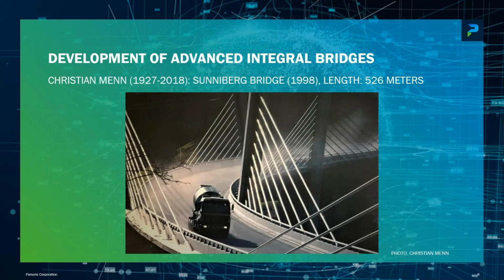And here you would say, what does this bridge have to do with Robert Maillart? Because this is a cable-stayed bridge. Some people call it an extradosed bridge, but I call it more a frame structure because the columns and the superstructure are monolithically connected, and as well the superstructure is monolithically connected to the abutments. So if the bridge undergoes temperature change, it moves radially in and out, and that is the same principle that Robert Maillart used for the Waldschild Bridge, just that he didn't move radially or laterally, he moved vertically.